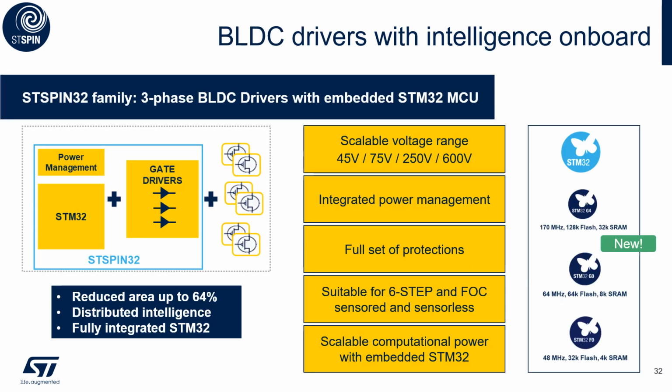The ST-SPIN32 family is a dedicated driver for three-phase BLDC motors with an embedded STM32 microcontroller. Here we combine in a system and package approach the power management, the microcontroller, signal conditioning, and the gate driver, and have an external power stage which gives us the advantage that we can target higher power application. We also reduce the space we need on the PCB up to 64%, and it's fully compatible with our STM32